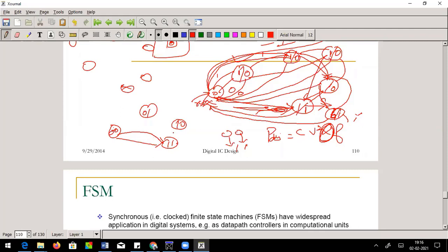How to code the state should also be known to him. It is not a matter of coding here, because I will show you shortly what the template looks like. That remains very simple, but the real challenge lies in developing an FSM with an efficient and minimum number of states, and coding those states with appropriate encoders.